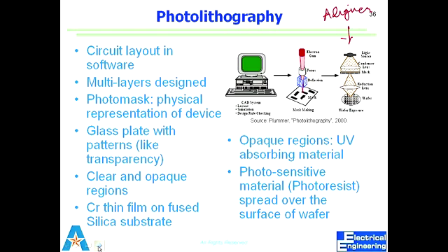So this is my mask, and I shine the light. Light travels through some optics, resulting in formation of this design in that photoresist material. Essentially, it doesn't make that design. What it does is change the property of that photoresist material in those places wherever that light reaches. Photolithography uses ultraviolet, 365 nanometer, 405 nanometer. So there are different wavelengths that we use. At that wavelength, that photoresist material which is coated on that wafer undergoes chemical changes.